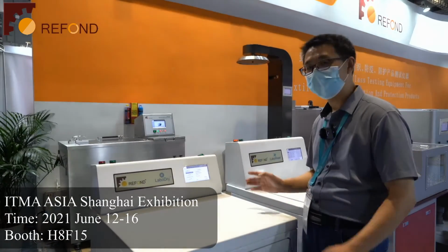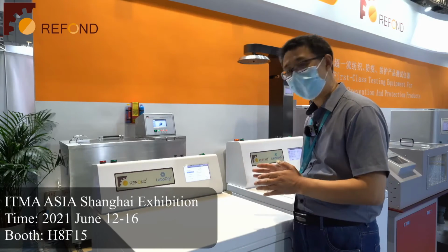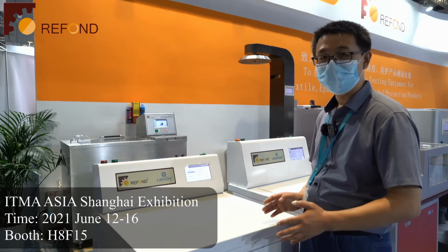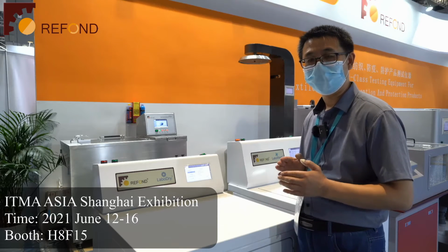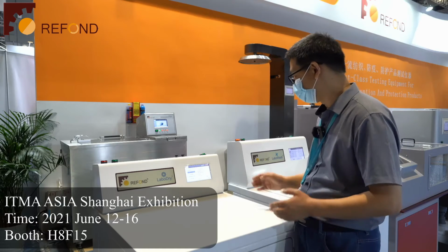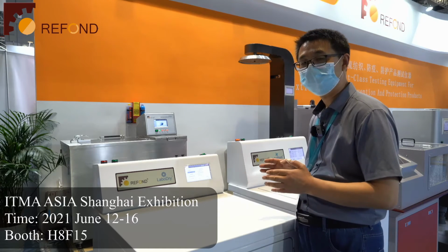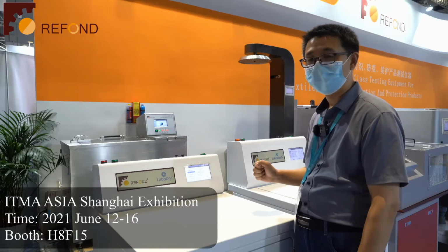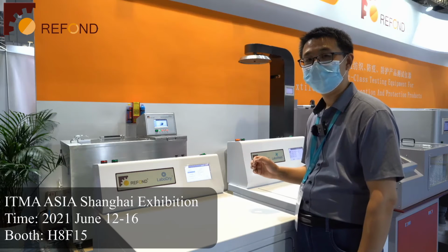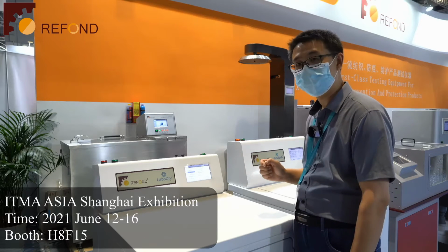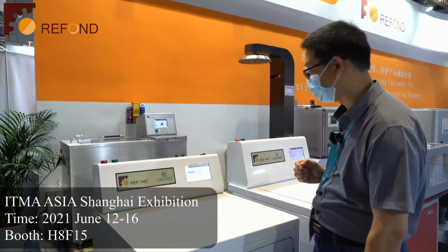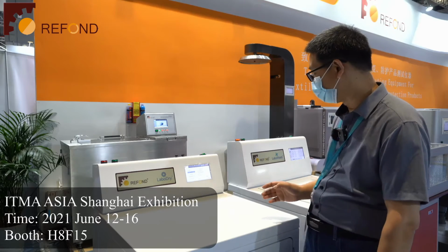As you know, if you set a fixed drying time for a certain fabric, you don't know whether the fabric has been less dry or over dry. So if you can set the humidity in the exhaust pipeline, you can monitor the humidity online or at any time. You can decide whether the fabric has been dry. So that's the new function.